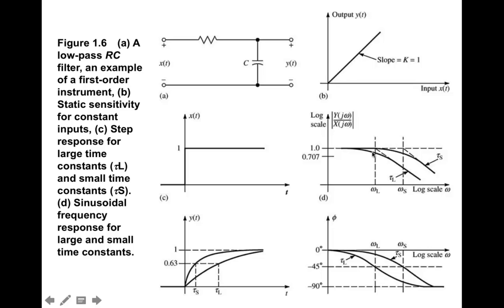And then as frequencies get high, the magnitude of the output starts to decay. So we will not have a constant output across frequency like we did in the previous example. The output actually decays as frequency increases. So for very high frequencies, we're approaching a zero output. And notice that our scale here is a log scale.